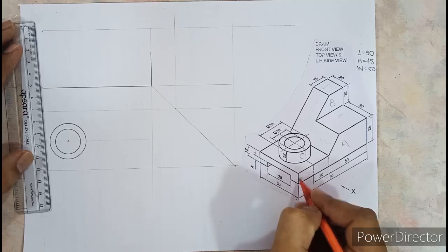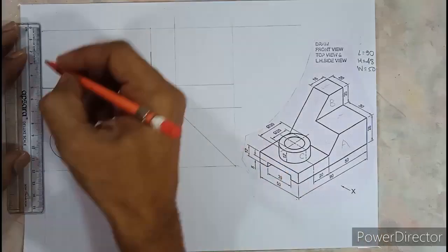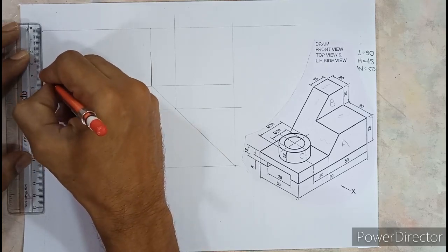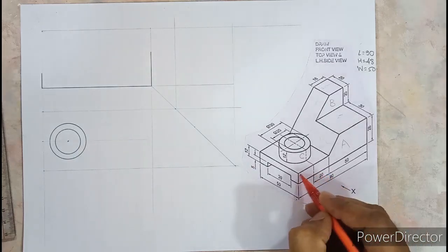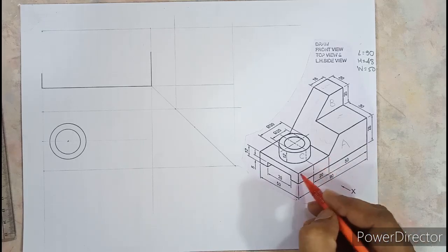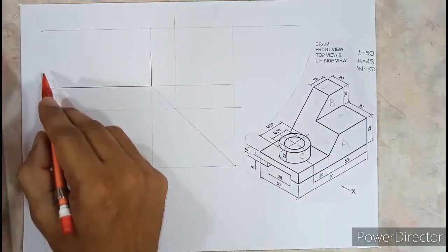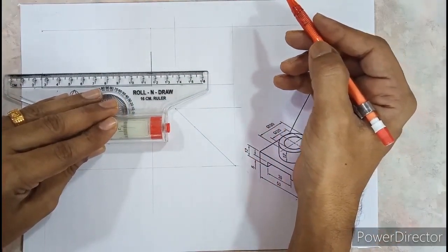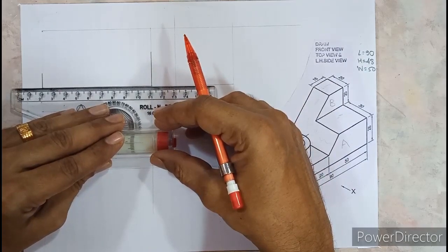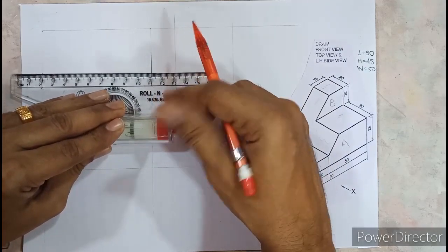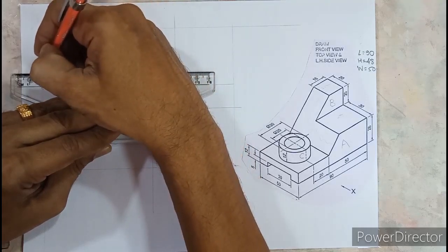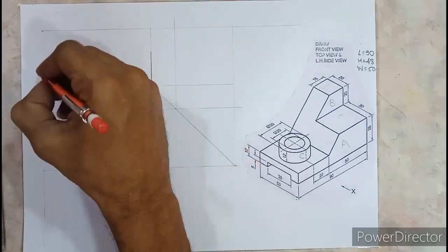On the other side we need to move up by 12 mm. See, this height is 12. So here we will be moving up by 12. Now look at this dimension. This dimension, either you have to leave 50 from behind or you have to mark 40 from here. So let us mark 40 from this side. So I will align the scale, slide up. Okay, so 10, 20, 30, 40. So till 40 mm I will proceed for the double trace. So always keep on double tracing.